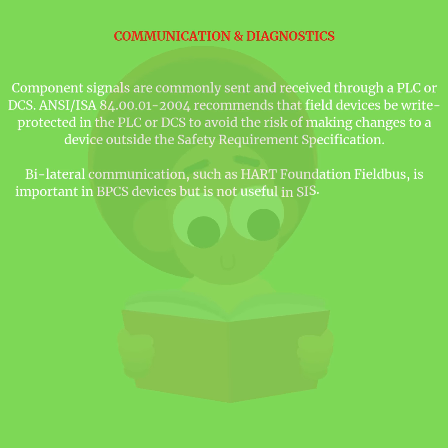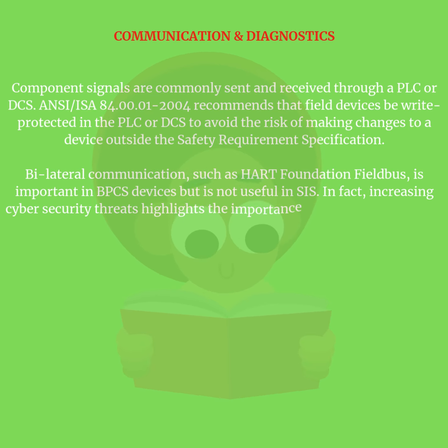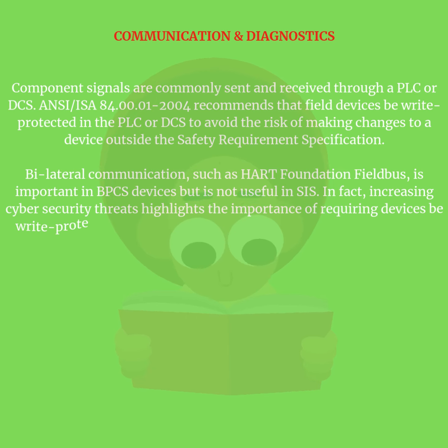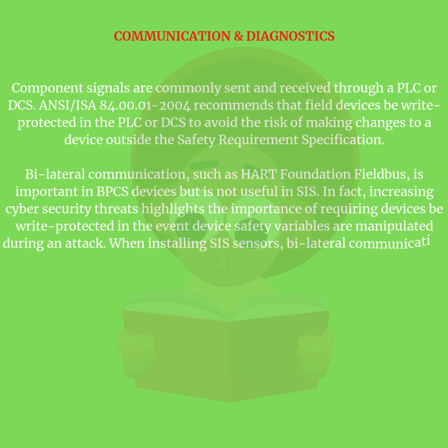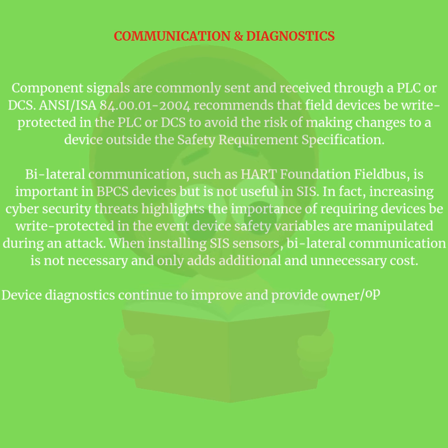Bilateral communication, such as HART or Foundation Fieldbus, is important in BPCS devices but is not useful in SIS. In fact, increasing cybersecurity threats highlight the importance of requiring devices be write protected in the event device safety variables are manipulated during an attack. When installing SIS sensors, bilateral communication is not necessary and only adds additional and unnecessary cost.